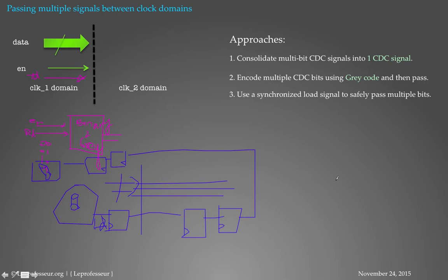So always remember that in a group of signals, only one signal should change in one clock when you are crossing from one clock domain to another clock domain. That is the basic, simple, fundamental rule you need to remember.